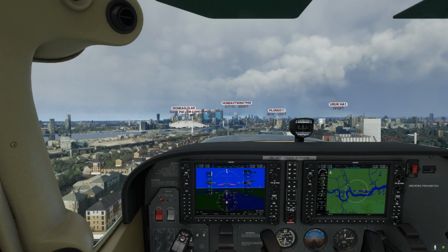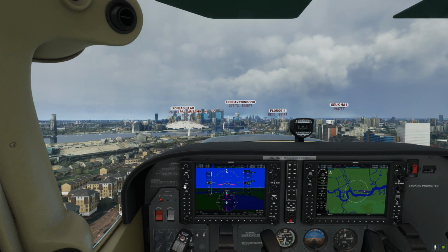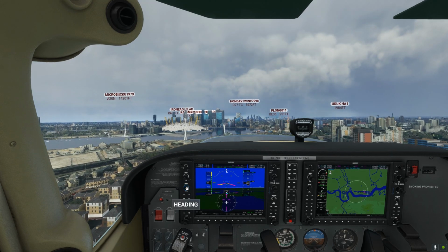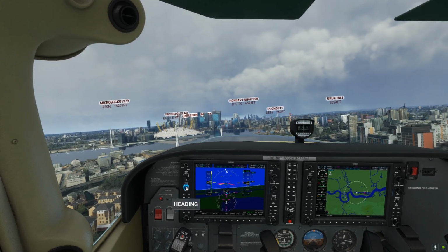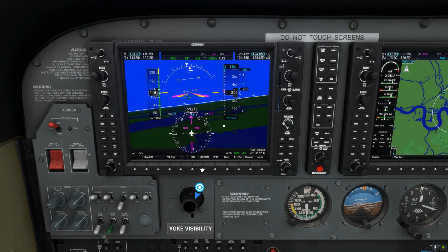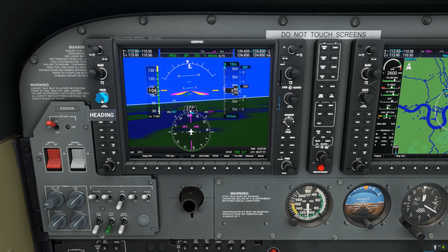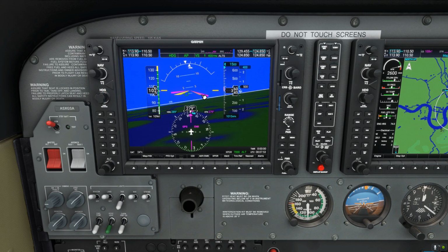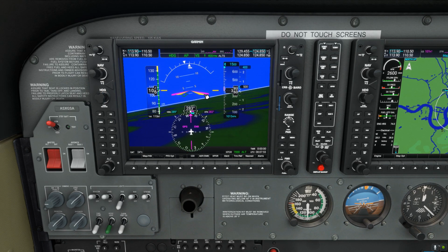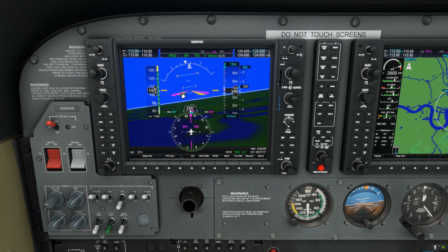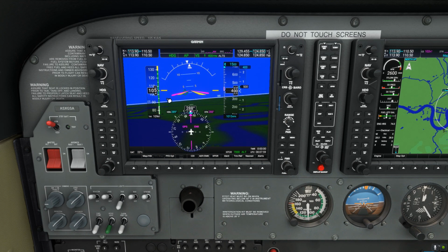That's fine. Just going to move, I'll do it in the actual cockpit here. Move my heading bug to the right there. And actually, let's come down and show you this. So if I move my heading bug, mouse up on my heading, see the purple lines? The flight director is showing the autopilot where it should be pitching to follow that course.